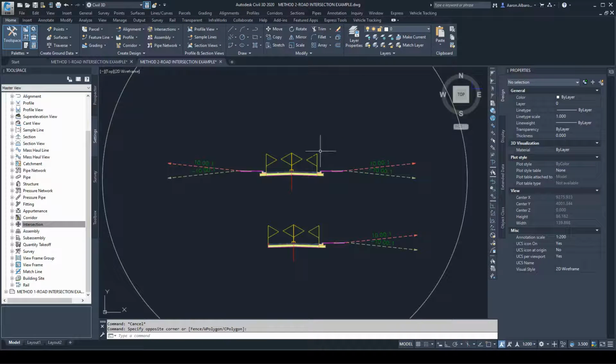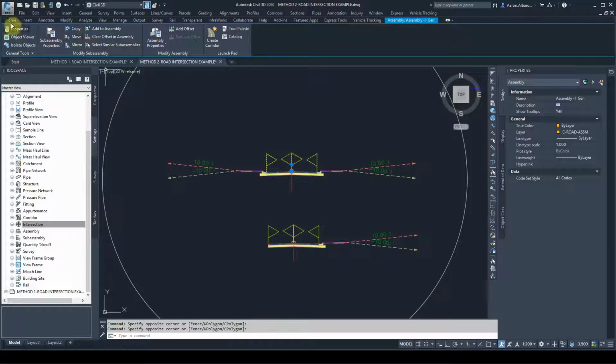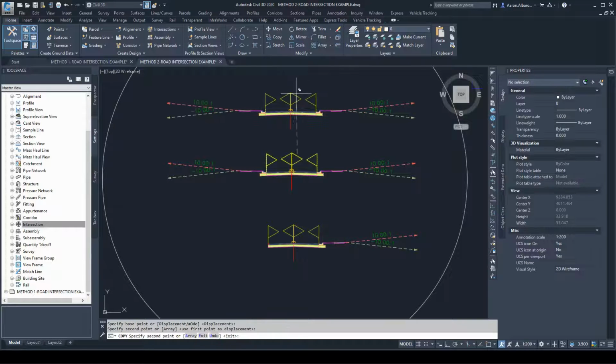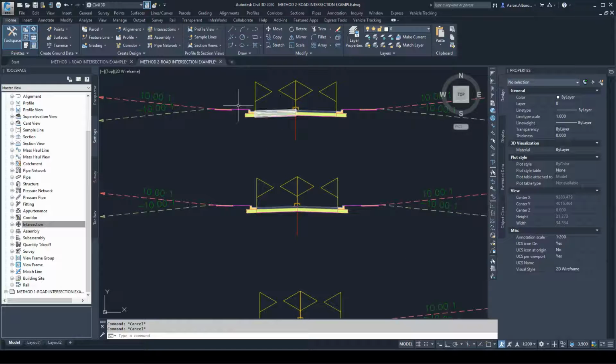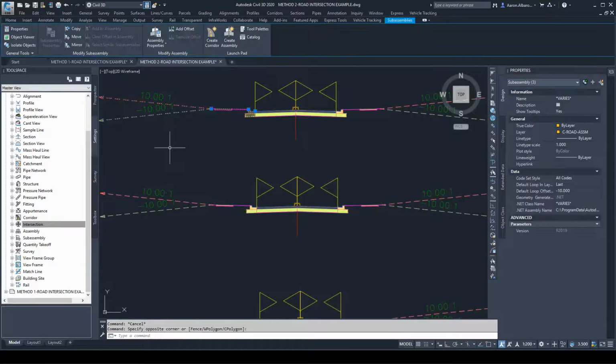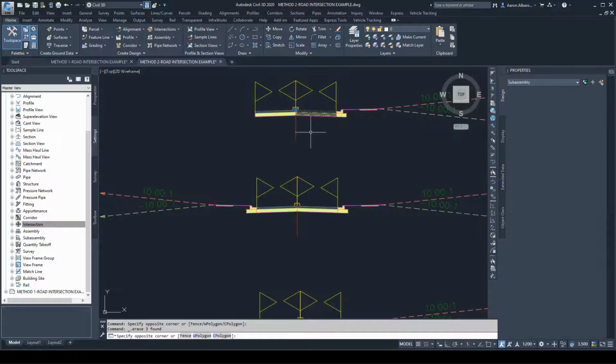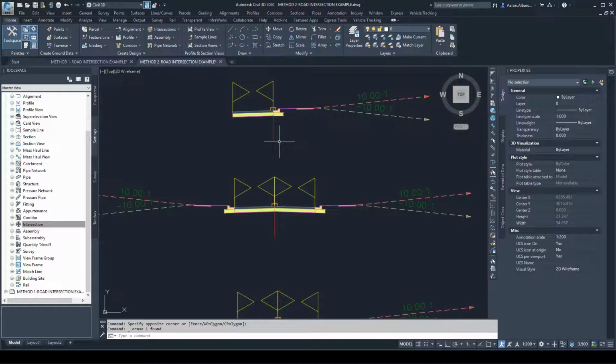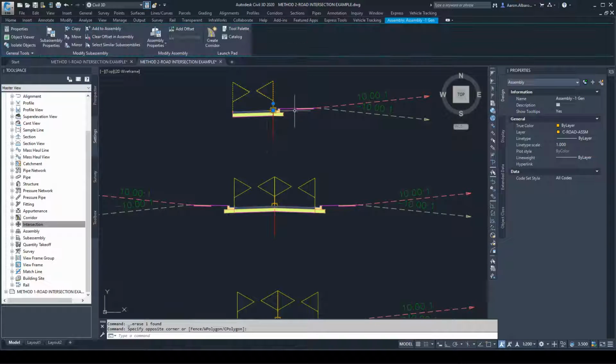So if I create one of those, I'll copy this. Lane to the left, this should stay. All of this, I don't need. And all of that to the right. I don't need the lane to the right. Okay, so we'll call it curb return right hand side, because the curb is on the right, that's the name convention I use. So curb return right hand side.